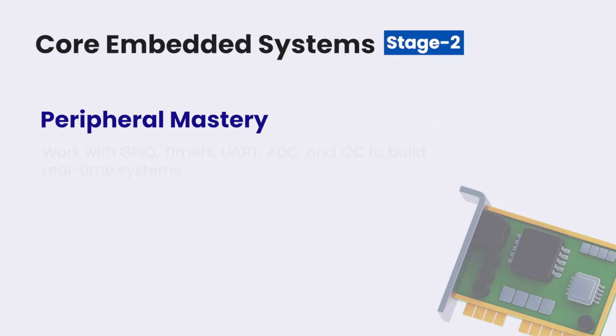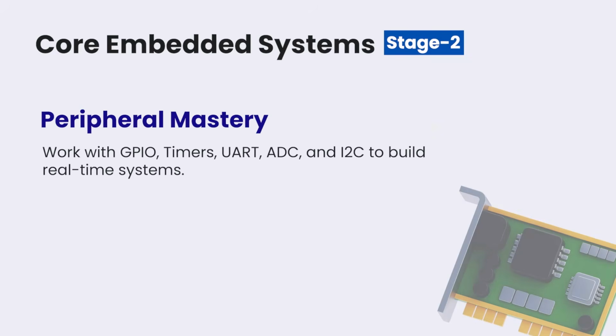So microcontroller programming can be done in different methods. One is you can start with a bare metal approach, wherein you learn to program everything from scratch. This approach requires you to understand the peripheral interfacing by reading the datasheet at a detailed level. You'll end up creating your own header files by defining the registers. You will end up writing your own low-level drivers, post which you're going to build the applications.